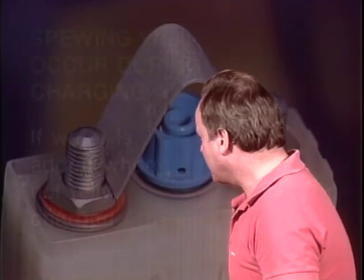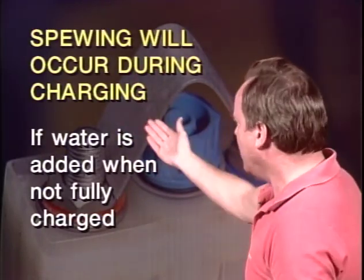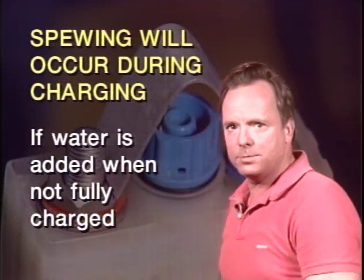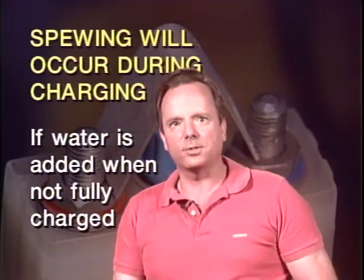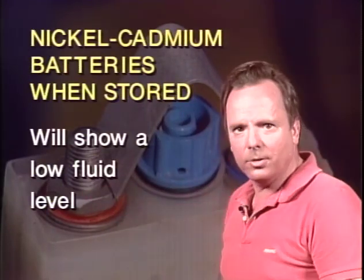Okay, now, remember we said earlier the level in a NiCad battery is lowest when it's discharged. So what would happen if you add water to a NiCad battery when it's not fully charged? Well, the answer is you'd have spewing, excessive spewing, the FAA says, if you add water to a NiCad battery when it's not fully charged, because the level automatically comes up when it's charged and then you could spew it out. Because at the end of a charging period, a NiCad battery tends to put out some gas. Nickel-cadmium batteries, which are stored for a long period of time, will also show a low fluid level, and you need to know that.